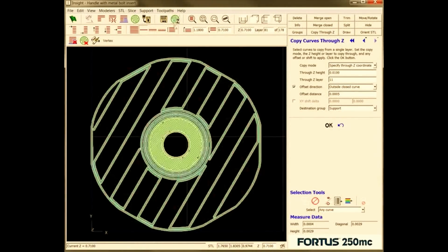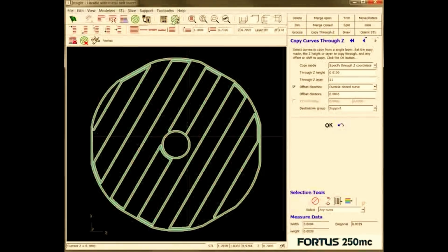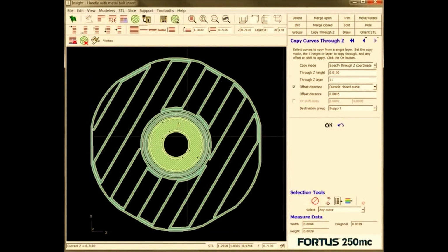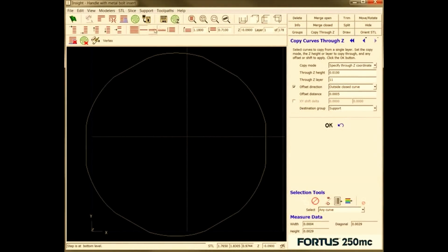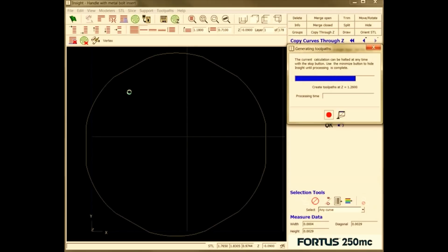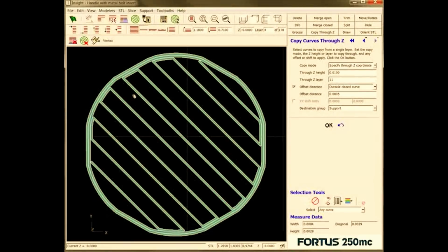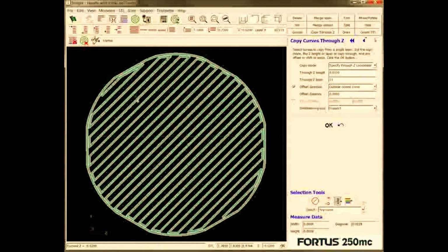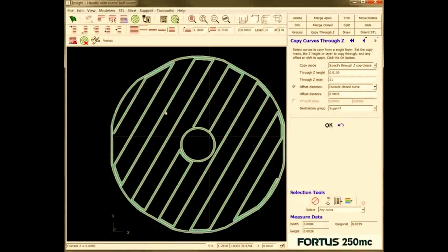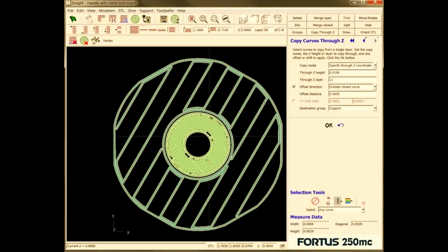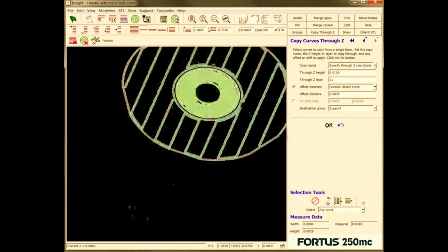and I do the toolpath for it, that's not going to be very strong, and it's also not going to give us a support face for this model material to draw upon. We always have a support face that creates a nice layer of support for our model to be drawn upon. If I went down to that very bottom layer, you'd probably see that. If we redid the toolpath for all of this, you kind of see the range. So you have your sparse support, and you have some regular support, and then we have the support face right there. So we need to create that way up where our model is going to start being drawn upon, right? Way up here.